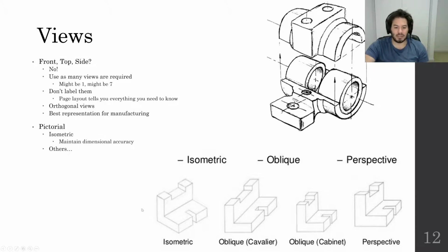It doesn't give the most realistic view of an object, though. It doesn't look quite right to do proper isometric views of things, because as we know, as things are further away from us, they are smaller. So a perspective view does that. It makes parts that are further away from you, so that line isn't as long as that line. It makes things look more realistic, more like a photograph, but less useful, because do you actually know, is this thing shrinking, or is it just the perspective? You can't measure things anywhere near as easily on a perspective view. It's for architects, is what it's for. Looks better, doesn't communicate as much information. It's for architects.